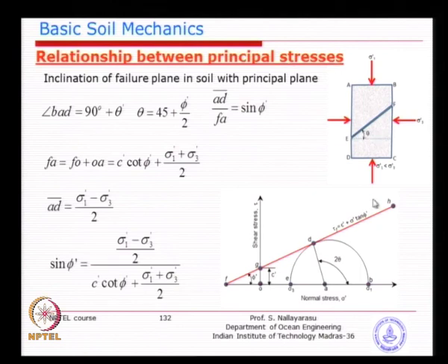So, when you look at this picture, when you put it in Mohr envelope or Mohr diagram, you can see sigma 1 is larger and sigma 3 is smaller. Basically sigma 3 is here, and if you look at the triangle in this using a similar triangle principle, you can see here AD and BAD, basically this triangle and this triangle, you can get the properties.